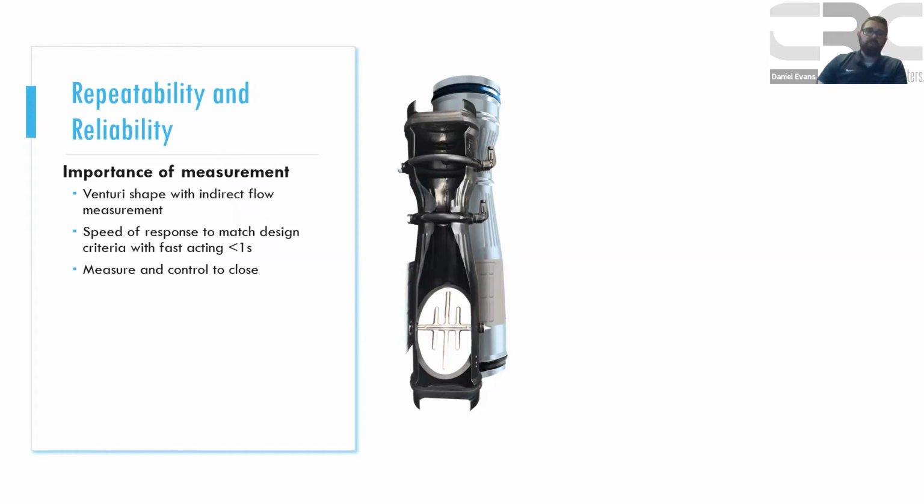What's one of the areas that impacts this? We talk about a 10-to-1 turndown, plus or minus 5%, but what's nice is you can actually take this air valve all the way down to close and still have feedback all the way down to close. So in some of our design scenarios, we may have a system that could be allowed to close off depending on something else happening inside the space. We don't have to have that 90 CFM or 110 CFM minimum that we might see in some other technologies, always going through a section just because it's that minimum flow rate.